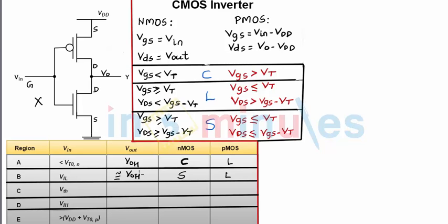Now we go to the case 3 or switching threshold. Now switching threshold is, remember, different from the threshold voltage. If I have a CMOS inverter and if this is my voltage transfer characteristics, Vout and Vin, my output is going to remain high for a certain period of time and after that it's going to go low. This is an ideal case.